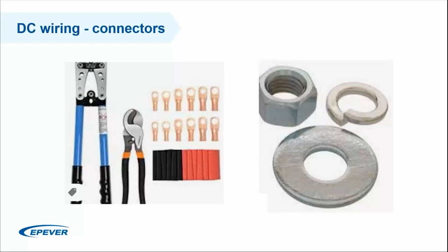And also, it's important to note that the tightening torque is also important. Sometimes we break a lock or a part of the wire because we apply a very high tightening torque for our equipment and for our locks, and this is also not good. It's better you use a sort of machine that has a predetermined torque, so that you do not create a resistance variation between your connectors.